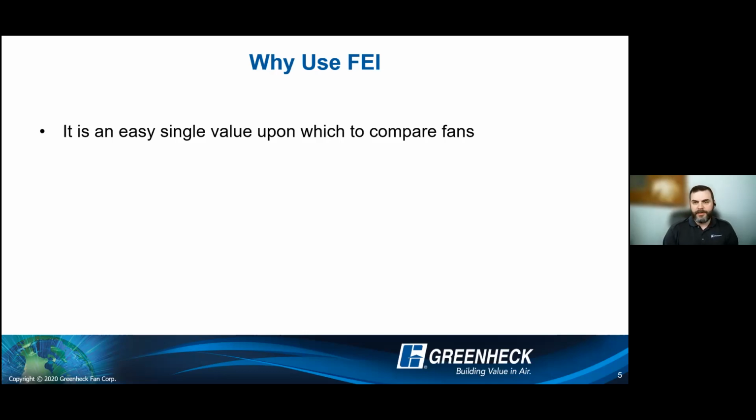I'm looking at the cost to operate, which actually coincides with FEI numbers, so not surprisingly. So I'm looking at the cost to operate, the cost of the fan, the performance of the fan. Of course, I'm looking at horsepowers and brake horsepower. Where am I operating? What kind of wiring? What kind of motor protection do I need?